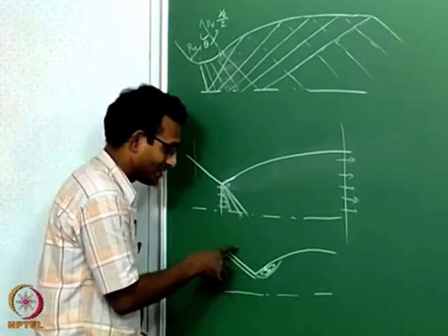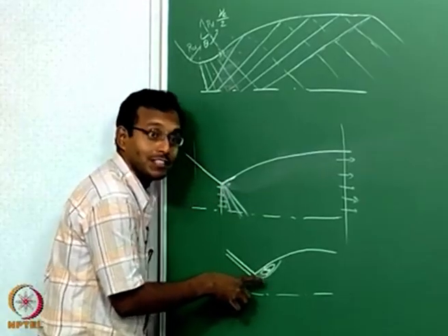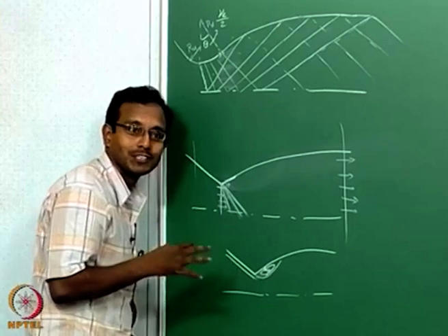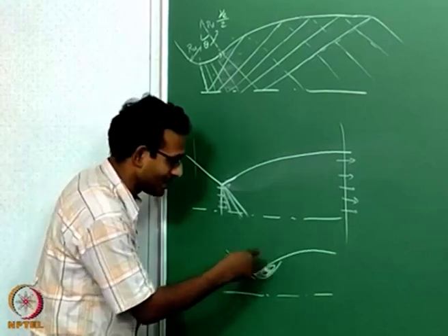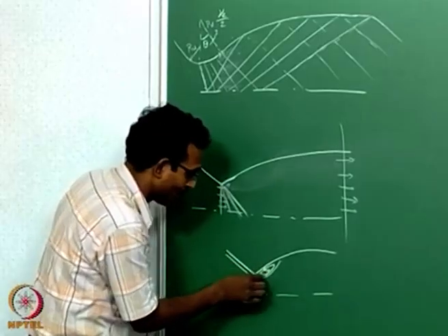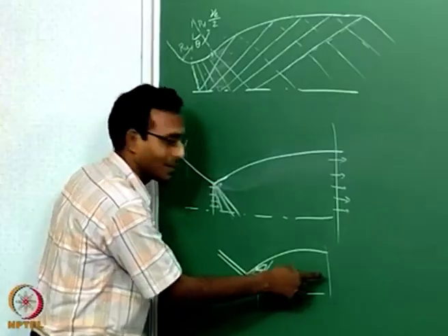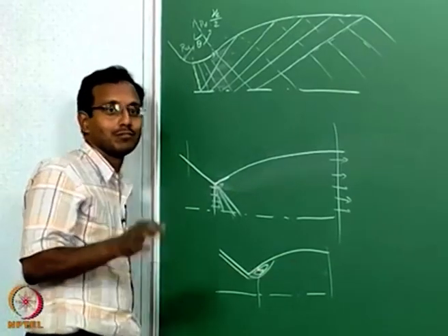Because of this, your nozzle does not have a real throat here, but some other throat, which is a moving throat. It is not a constant throat, because there is an oscillating recirculation zone. It will be changing shape once in a while. So your A by A star is never fixed, so you will not get the correct Mach number at the exit, and it is not a steady flow.